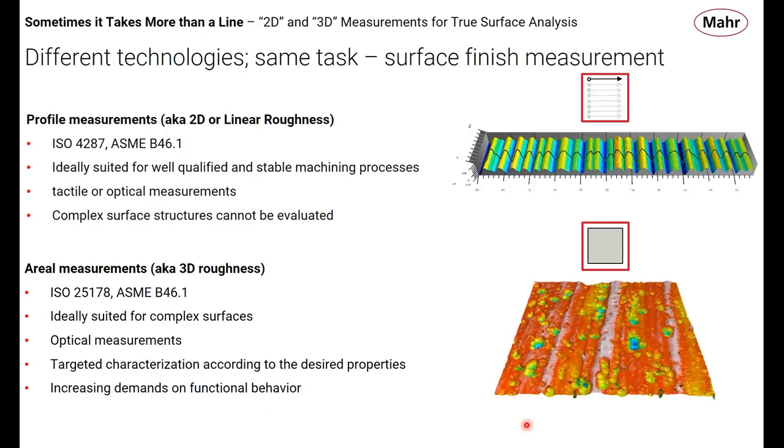This technique, these profile measurements, are very, very well suited for well understood processes, well understood machining technologies. And what I mean by that in the concrete context is we know a process is stable, a process is well suited for profile measurements when we know we can monitor that RA value.